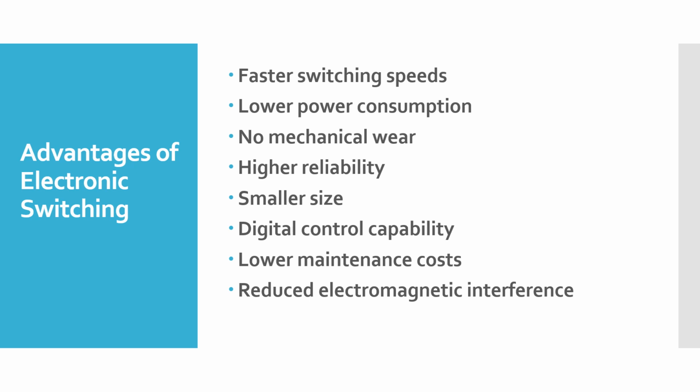By the time you start tugging your changeover switch over and over, with time it will wear off, it burns, with high heat occurring in most of those. But by the time you've calculated your load and put it into consideration, electronic switches are small. Can you imagine how big a 100 amp changeover switch is, with all these knife edges?